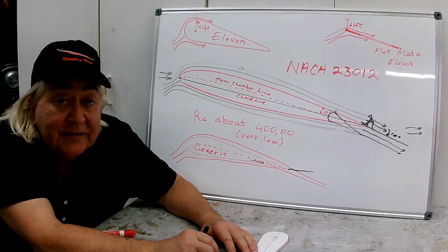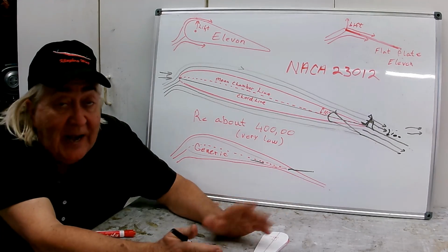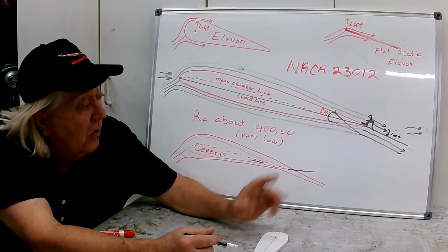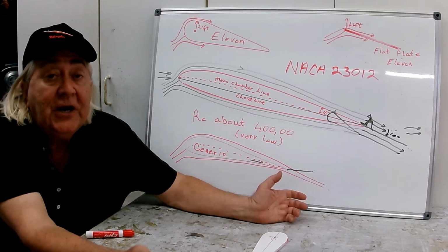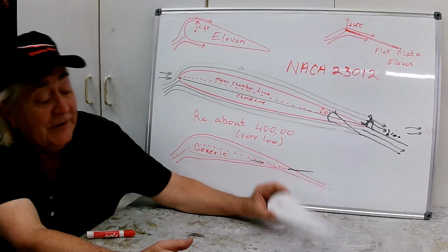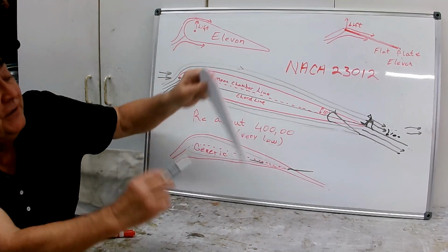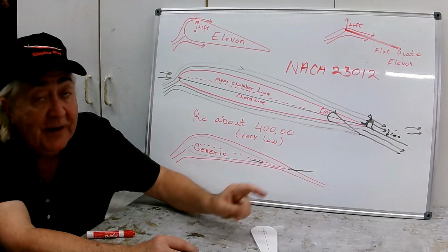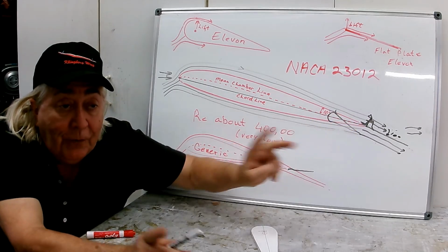So it's really the same answer. It's not like there was magic here that all of a sudden, a flat plate can go to a much higher angle of attack. It can't. It can go at about 12 degrees, same as this guy. This guy gets up about 12 degrees and the flow separates off. Same here, but you got 10 degrees for free up front.